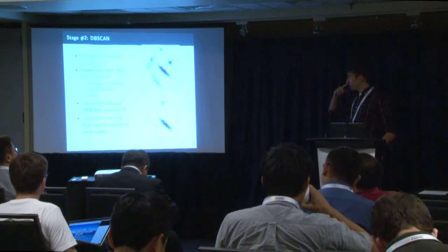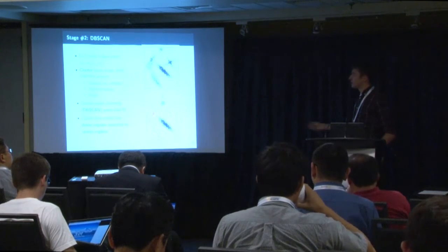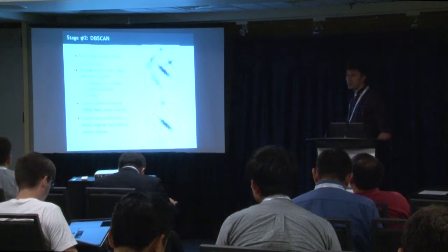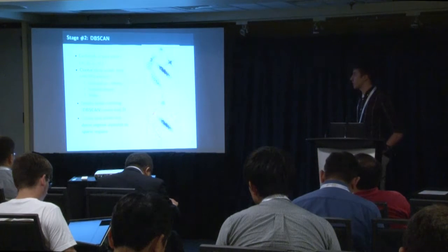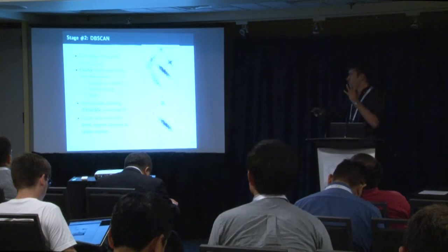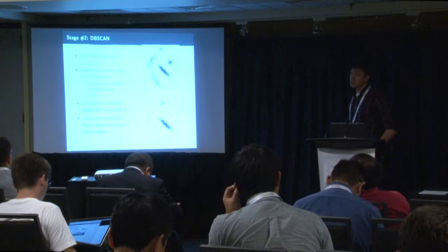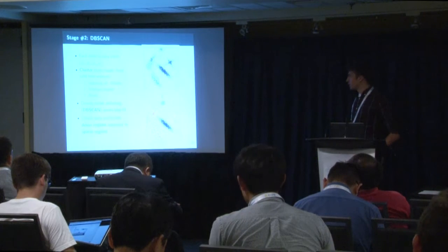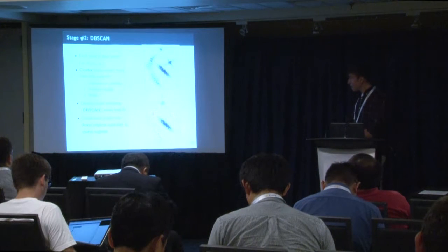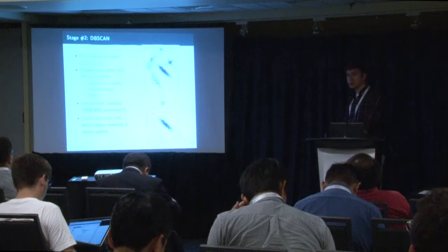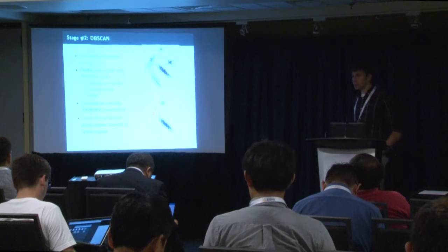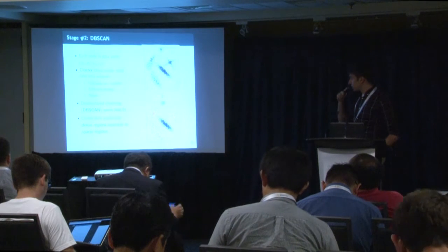Now, to cluster them, we cannot take just any algorithm. We need to really think about which clustering algorithm to pick, because we don't know the number of clusters, so something like k-means is not an option here. The shape of these lanes is usually snake-like, they can be curvy. So again, k-means is not really an option, because k-means can only find circular clusters, and there's usually a lot of noise. So we experimented with a lot of different clustering methods, which are all also in the paper, and we found that density-based clustering works best. We use DBSCAN for this.